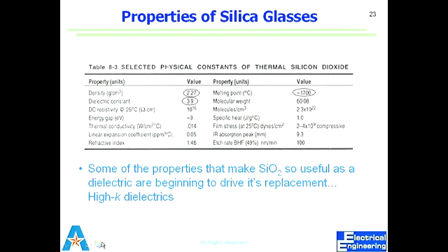Once you get into the lab and spend some time, it will be very easy for you to look at the color, look at the chart, and you will have a very good understanding of how thick the silicon dioxide is and how long you want to etch it to remove it completely.